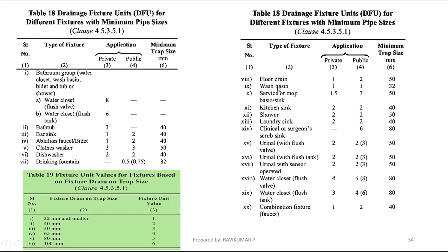Sometimes they have mentioned floor drain now. For that one, we are using 75 mm only, not 50 mm. You have to adapt as per the market also. So a 50 mm floor drain is also there, but we are not using a 50 mm outlet floor drain. Only a 75 mm outlet floor drain we are using as standard. So we have to keep that in mind.